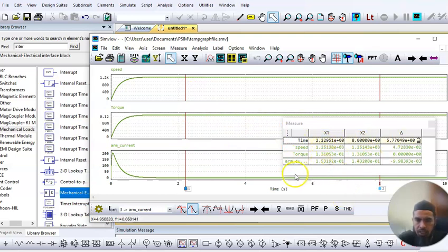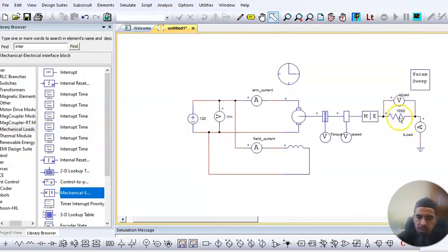So we set the highest possible, let's say 1000 ohm, to represent the output at this value. Let's say we want to analyze the machine when it operates from minimum load up to maximum load. 1000 ohm represents minimum load, meaning the higher the resistance, the lowest the current consumption. So this represents minimum load. So how do we set it up such that we can see how the performance changes when we increase the load gradually?